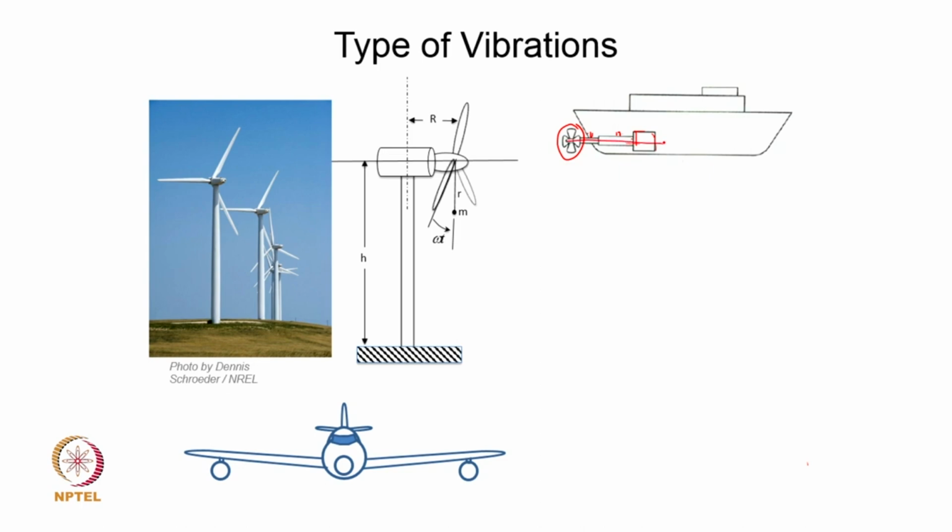In this case, vibrations along the longitudinal direction are quite possible, and of course this does not stop it from vibrating laterally as well. So, you will need to analyze and investigate the longitudinal vibration of this propeller shaft, and once estimated, the natural frequencies need to be kept away from the excitation frequency. The rotational frequency and its link with the natural frequency of vibration needs to be established to ensure that resonances are not set up anywhere.